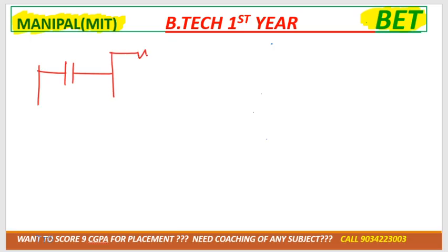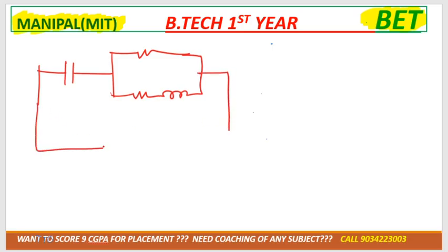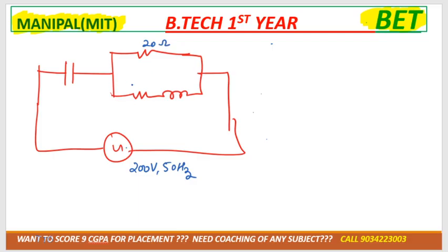This is from your PYQ paper only. A capacitor is connected in parallel with the resistor and the inductor, and the voltage supply is given as 200 volt, with 50 hertz frequency. This is 20 ohm, this is 5 ohm, this is 0.1 Henry, and this is 150 microfarad.